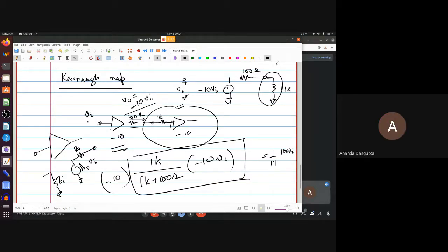Okay, and one more thing, of course, the gain here is of the order of 90 or so, but you have to be careful. Your input voltage should not really be very big because 1 volt input would not even anyway have given you a 90 volts output, right? If you are using op amps at least, it would go into saturation. But a 0.1 volt input would give you a 9 volt output and not a 10 volt output as a gain of 100 would have predicted.